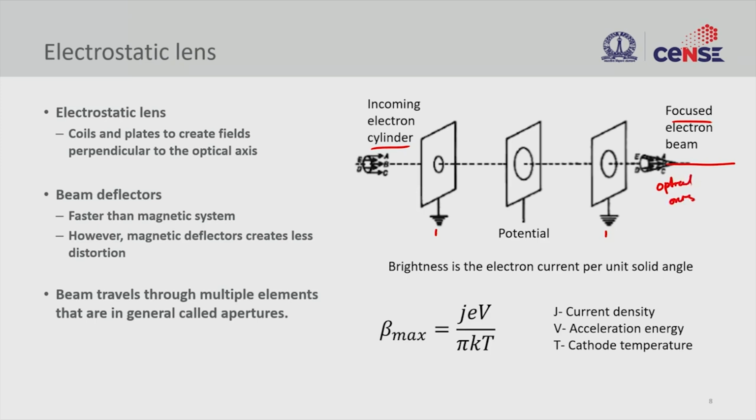If the beam is within the optical axis, you will capture it, and if you put a deflector here and apply a voltage, I can deflect the beam. If I deflect it, then I will not see that beam, or if you do a small deflection, I can change the position of the beam. These deflectors can be realized using electrostatic plates, but you can also use magnetic ones.